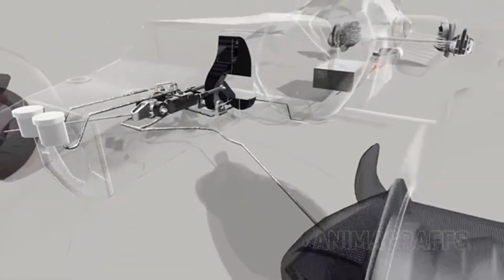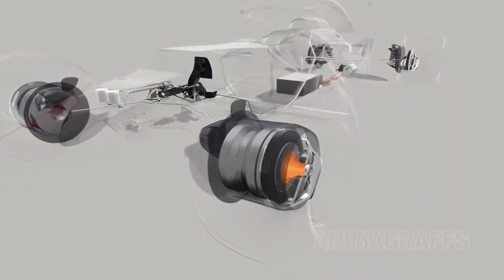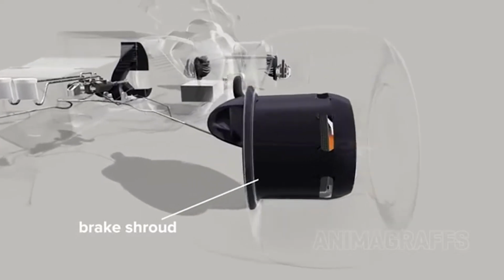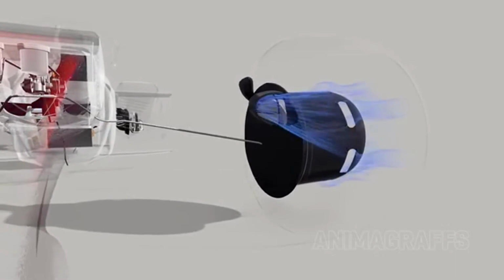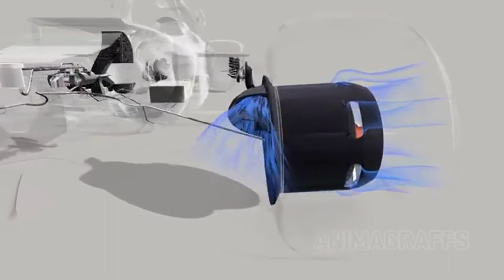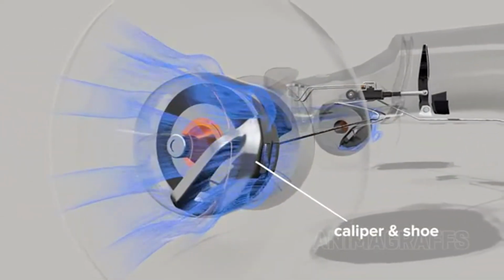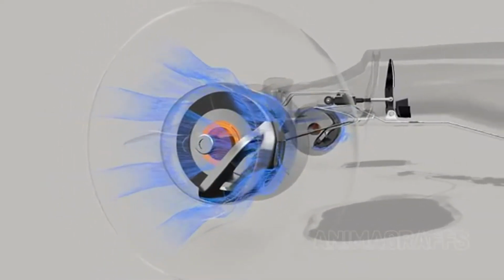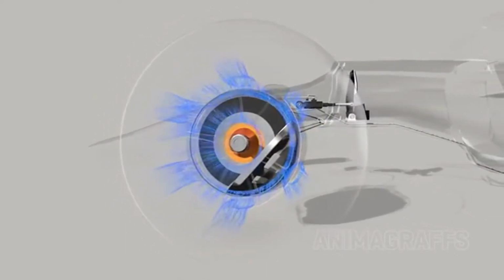Brake lines snake through suspension elements to the brake caliper and shoe assembly. Intense brake heat must be precisely managed, so the entire inner wheel assembly is covered by a ducted carbon fiber shroud. The front wing helps direct air into the brake ducts and through the inner wheel for cooling. The calipers are mounted at the lowest possible position for proper brake bleed. That is, ensuring troublesome air bubbles can escape hydraulic brake lines, while maintaining a low center of gravity.